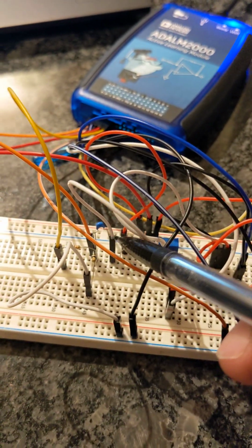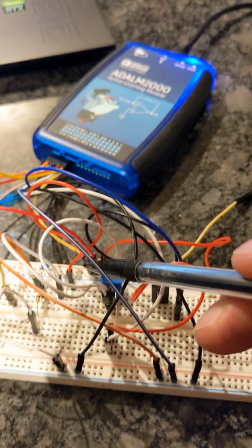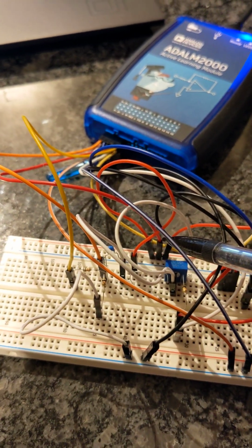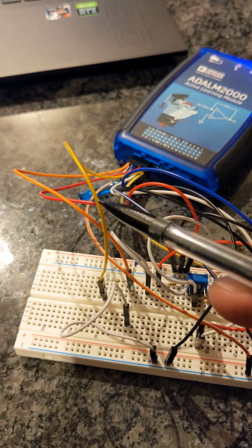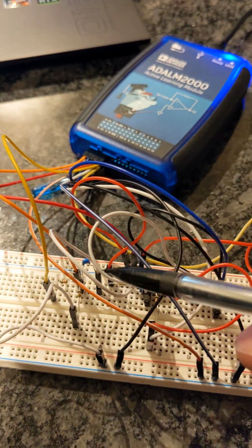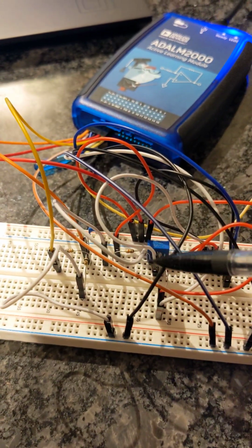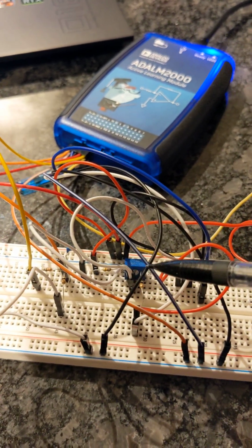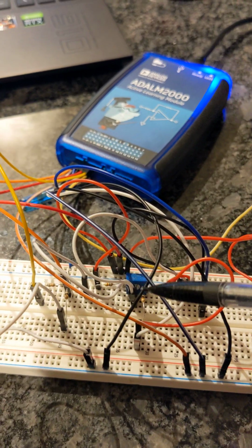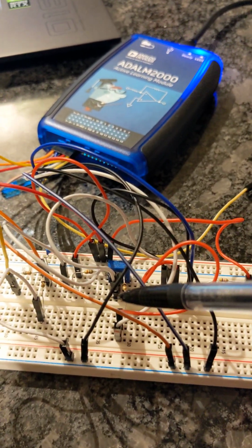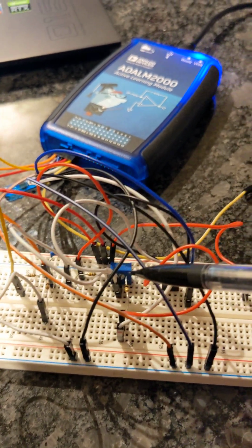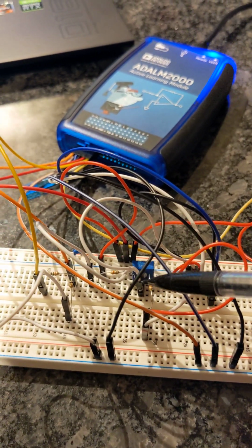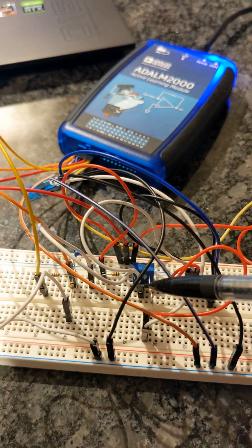This capacitor separates the DC components. We have power coming in at this top row with these three. The middle one comes from the board itself. You can see it. This one goes to this resistor here, and this resistor is the input of our potentiometer. That's R3. Our potentiometer is going to output whatever the lower end of this potentiometer is here.